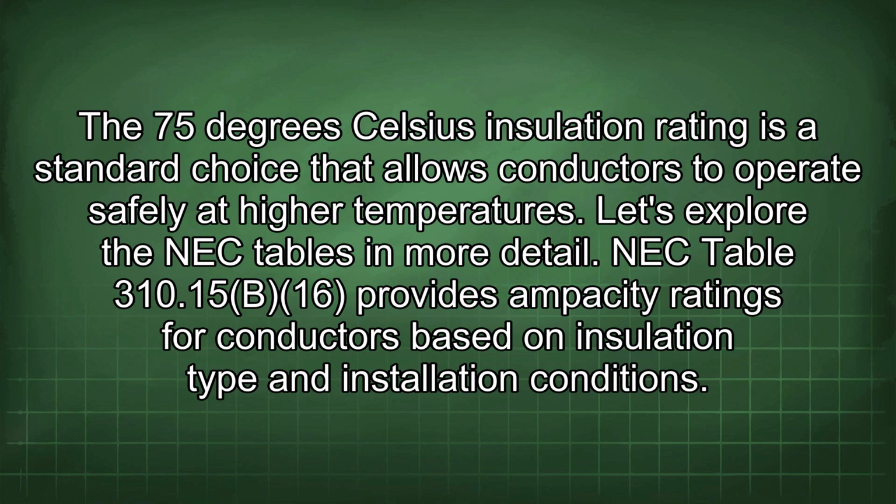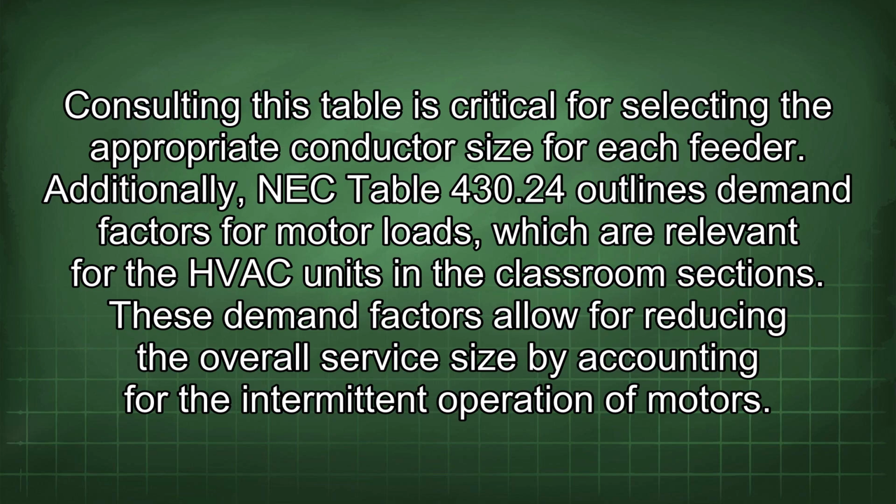Let's explore the NEC tables in more detail. NEC Table 310.15(B)(16) provides ampacity ratings for conductors based on insulation type and installation conditions. Consulting this table is critical for selecting the appropriate conductor size for each feeder.